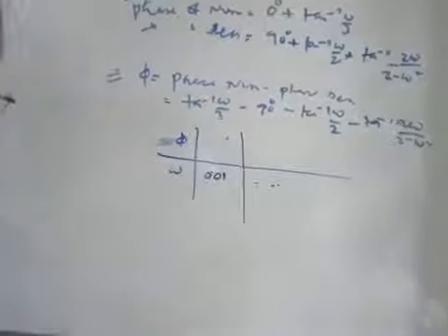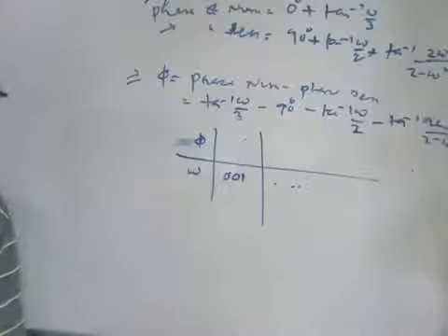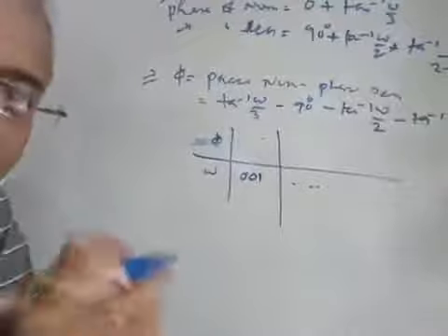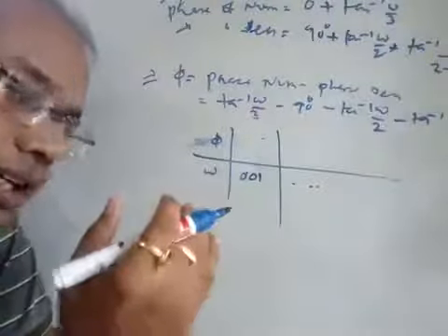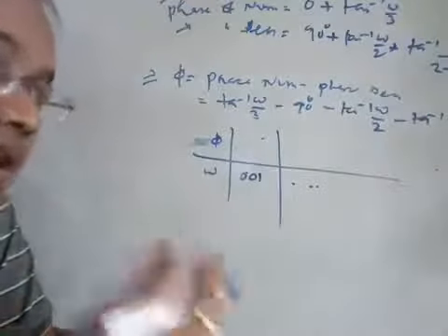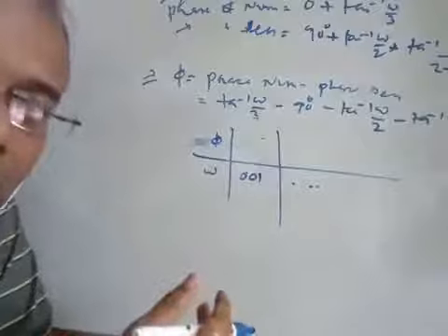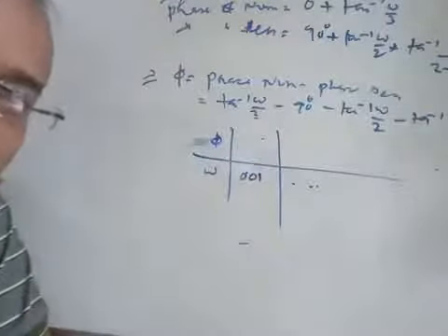And next, you consider the last frequency, which we normally take as 50 times larger than the maximum corner frequency available. And this is all about the Bode phase plot.